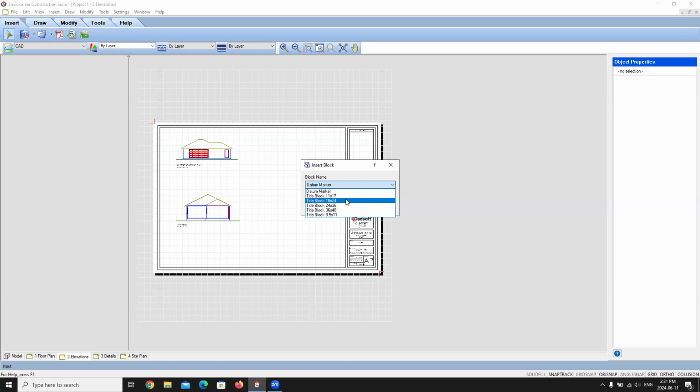So again, this could be something that you use in a template format. If you know you're going to be working with a smaller project and it's going to fit on an 11 by 17 or an 18 by 24, then you can have a template set up so that it prints to those sheets for you already. So you don't need to do this setup every single time. You would just select that template from the start when you're working with your drawing. But if you ever do need to make an adjustment on the fly, you can just simply add in the title block that you want.